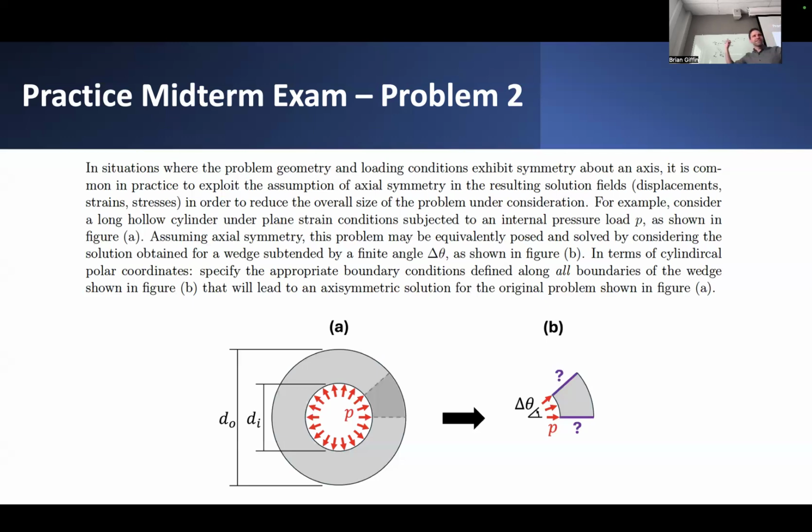So in this case, if I'm saying that on this exterior circular arc, I'm not imposing any kind of stresses, no tractions are imposed there, what does that say about how these resulting components of stress should appear? Yeah, basically, at least visually, it doesn't look like I'm imposing any displacement boundary conditions. So the only thing I'm imposing here is traction boundary conditions. And traction boundary conditions can be zero stress conditions.